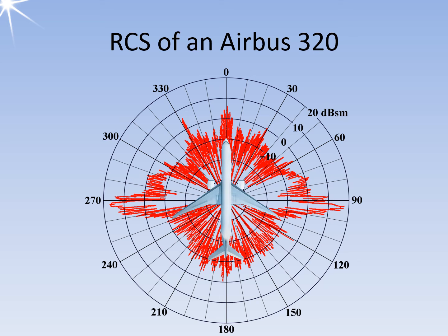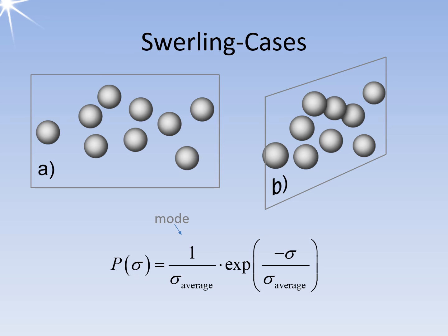These fluctuations of the radar cross-section were mathematically analyzed by Peter Swerling in 1954. The Swerling models describe the statistical properties of radar cross-sections of objects with complex surfaces. According to the Swerling models, the radar cross-section of a reflecting object is based on the chi-square probability density function with specific degrees of freedom. The chi-square distribution results when independent variables with standard normal distributions are squared and summed. There are 5 different Swerling models, numbered with the Roman numerals 1 through 5.